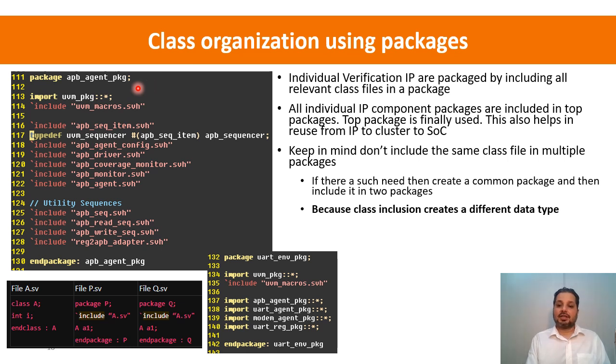So what is an agent? You will understand when we go to UVM. So let's for now just take it that it's just a combination of your driver and monitor and some more set of classes. So I have package APB agent package, and then I'm importing UVM package over here because I am using it in the rest of the classes, and I have to do so whenever I want to use UVM. I need to use these two lines: import UVM package, scope resolution star, tick include UVM macros.svh.